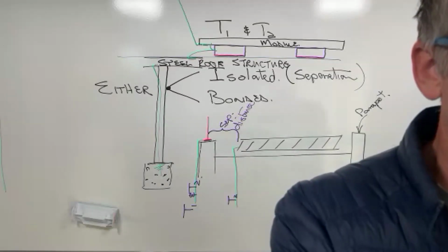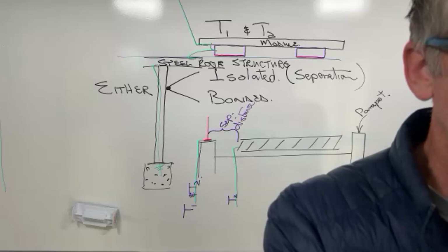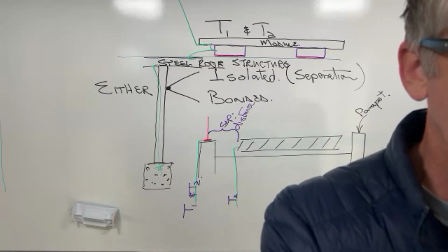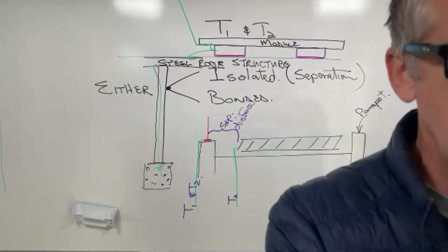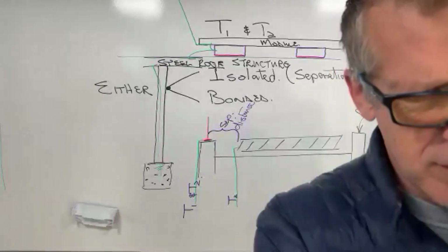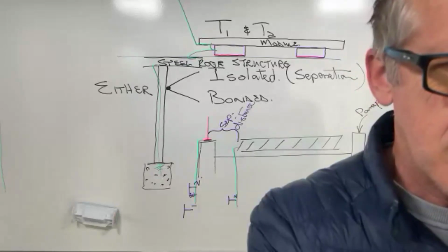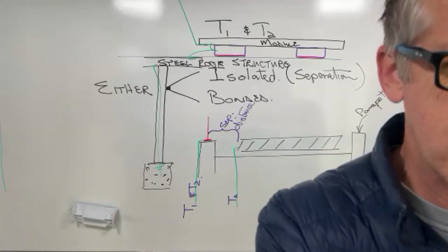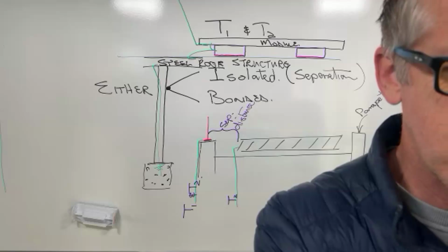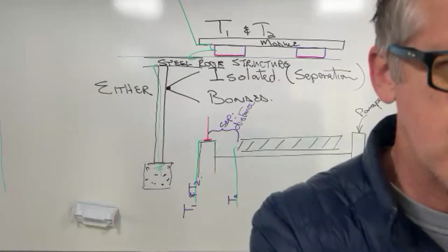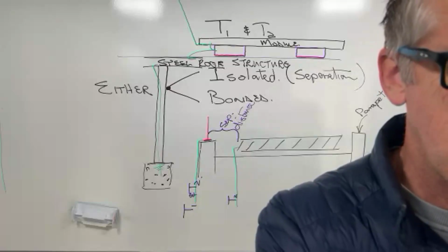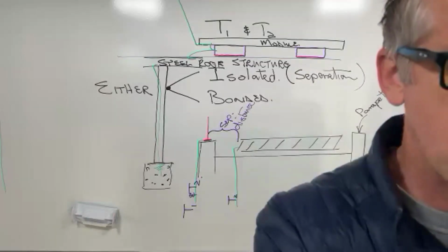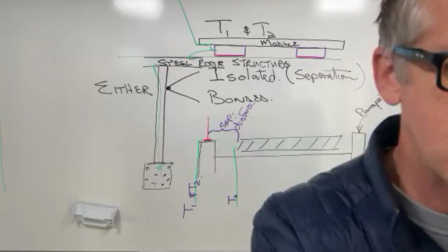Ruan says, we found that buildings are non-compliant in terms of lightning protection, bonding and earthing of their steel structures and roofing. That's quite true, especially if you're looking at the older buildings. Then Ruan says they expect you to do lightning protection, bonding and earthing only for the solar system. In my opinion, you can't do partial installations. The complete site needs to be compliant. When we advise clients on this, we always end up being more expensive than other installers.